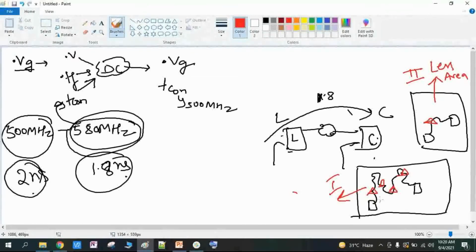So what actually happens if you have relaxed timing? For example, instead of 1.8, if I need to meet 2 nanoseconds itself, then obviously the tool will have relaxed timing and can easily meet it. It doesn't need to add a lot of buffers to bring this net down to 1.8. It needs to make 2 nanoseconds only. So maybe if I add 2 buffers only, it will make it 2 nanoseconds. Clear enough?